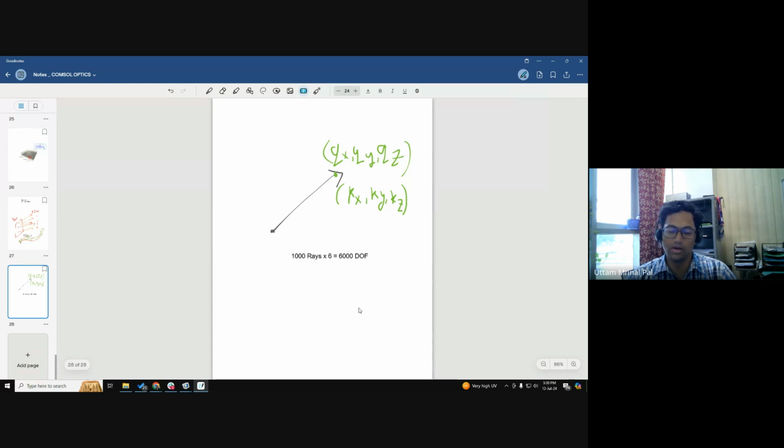The rays do not need a domain to propagate. Like what you see in ray optics, in wave optics, as you have seen, it needs a domain to propagate, right? An air domain needs to be there, but here you do not need to. You just need to model only the interfaces. For example, we are going to model one kind of plane wave, which is one kind of surface that is going to launch the rays, and then we're going to model a lens which is going to focus this light source. Okay, a simple thing that we'll model.